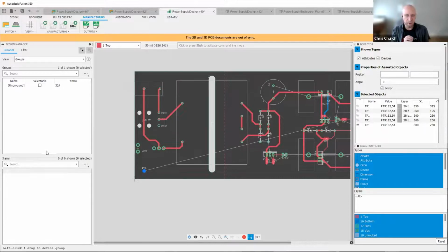But with the ODB++, you can export that, upload it to us, and we can extract your bill of materials, the part placement, the board design, everything from that one file. And with MacroFab, it is truly a drag and drop. You'll literally say create new PCB, drag your ODB++ file in, and a few minutes later you have a price and you're ready to go.